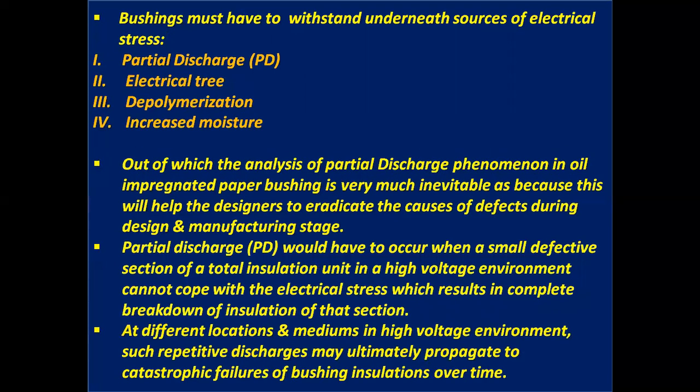Bushing must withstand the following sources of electrical stress. 1. Partial discharge, electrical tree, depolymerization, increased moisture. These four are very important.